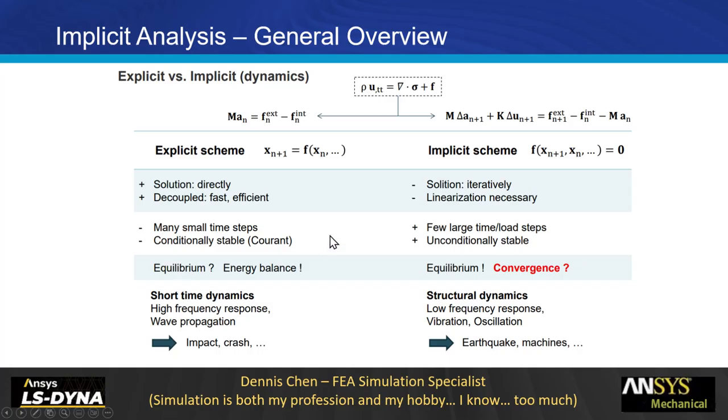For the most part, right, Dyna is used for explicit analysis, in which you usually solve the problem directly, taking very, very small time steps, like stable time increments. Usually you don't have to check for convergence, and you can handle problems that are highly nonlinear, but usually of very short durations. And these are very good types of problems for explicit models, right?